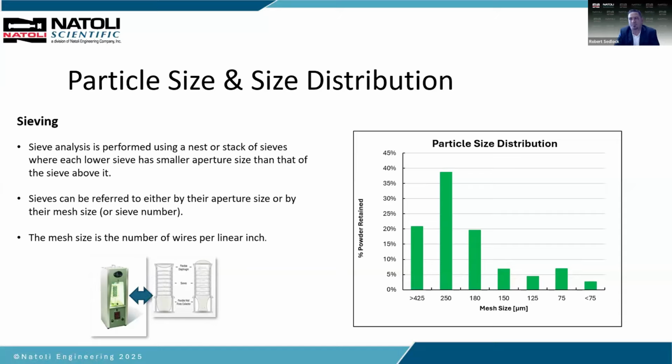So the tablet actually caps or delaminates. But as a formulator, it is important for us to know what the solid fraction is and the porosity. A solid fraction of 0.8 means your compressed density reached 80% of the true density with all the air removed. 1 minus 0.8 gives us 20% porosity. That's kind of normal for swallowing a tablet.